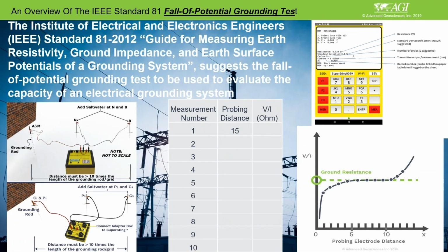The other thing is the electrical engineering standard, what we call IEEE 81-2012. This is what we call typical fall-of-potential ground testing. So we need to show these structures, like what you need to protect: your structure, your machinery, whatever is to be protected. Then you need a ground and grid.